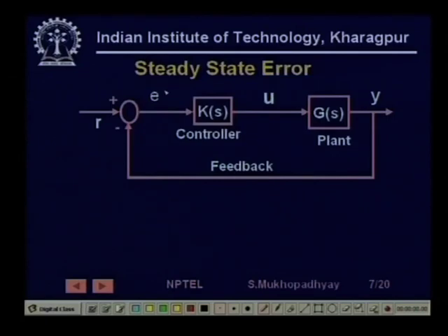This happens for a lot of process equipment. So, if you have performance degradations which persist during the phase when the set point is held, that is generally considered much more serious than errors that can occur when the set point is changing, or immediately after that for a short duration. So, we would first like to ensure steady state performance, and the major consideration for that is steady state error.